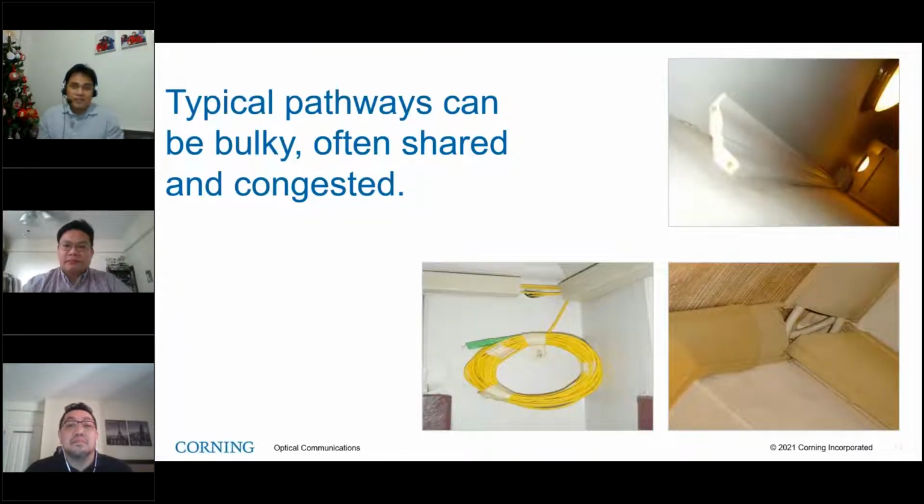Despite the several advancements in FTTH technology, service providers deploying FTTH in MDUs still face the challenge of running fiber cable from the hallway node into the living unit. Traditionally, in older buildings, pathways for routing cables in hallways didn't exist or were too congested with existing wiring, and new ones had to be constructed. These pathways were often bulky, expensive, and craft sensitive, such as crown moldings or plastic raceways. Once the pathways were built, drop cables were placed by pulling or pushing one at a time to complete the installation process.